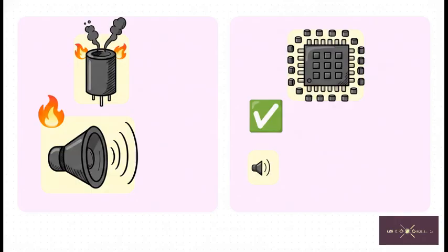This is way different from a true short circuit, which will practically scream at you with a really loud, aggressive beep, show a reading at or very near absolute zero, and will immediately draw massive amps if you hook it up to a DC power supply. Knowing the difference between that natural CPU beep and a true destructive short is absolutely essential.